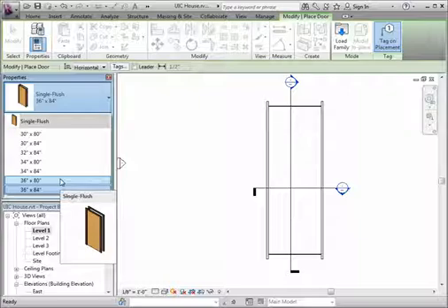If you wanted to make a custom door, you would get into working with families. Families is how Revit is organized. I mentioned at the beginning that Revit is organized into different building groups, which they call families. So a door is a type of family. A light fixture is a type of family. A piece of casework is a type of family. So if you want to make something from scratch, you would have to make a custom family.